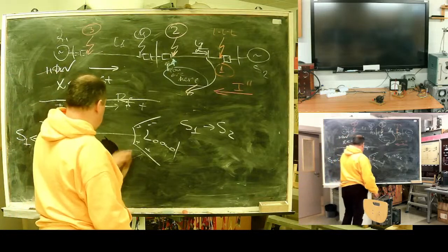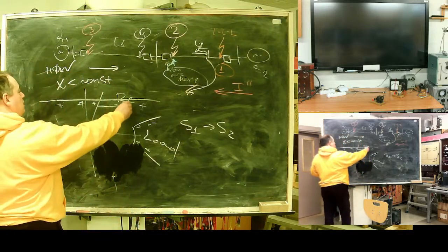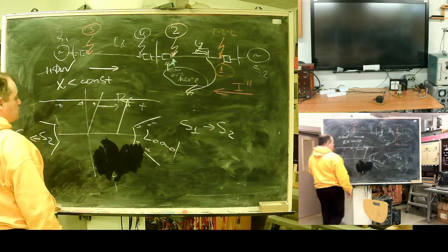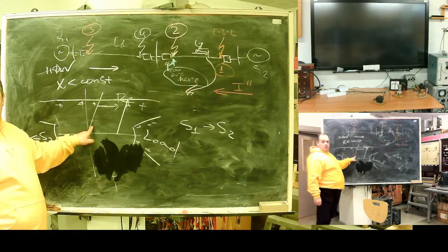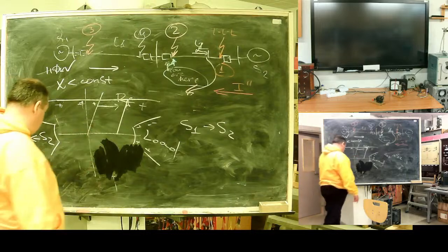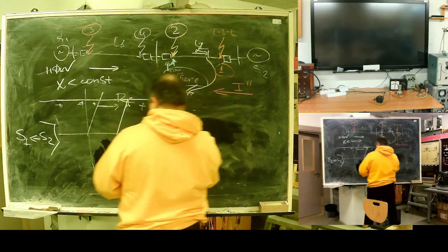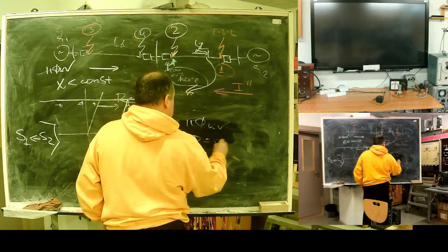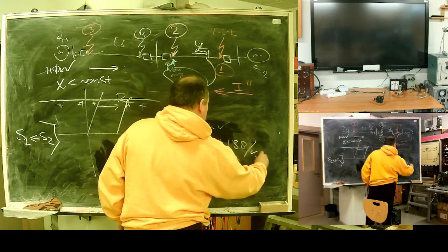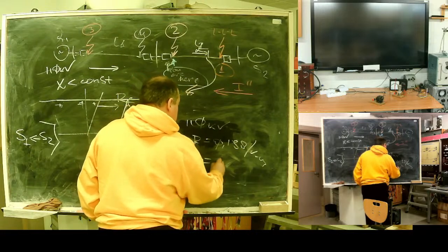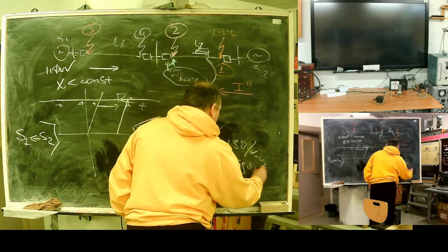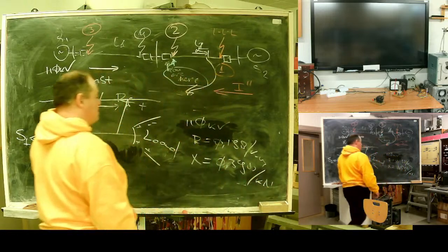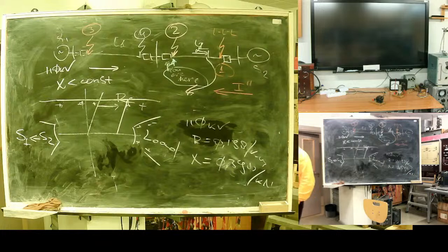That's why usually something like this is used. A simple line parallel to the expected line resistance. So if you have, let's say, a 110 kilovolts line, active will be approximately 0.19 ohm per kilometer, and X will be something like 0.49 ohm per kilometer of length. The angle will be somewhere 63, 65, 70 degrees, something like this.